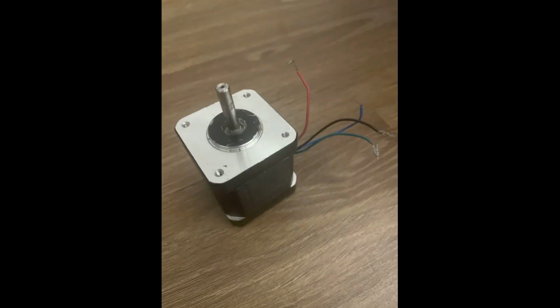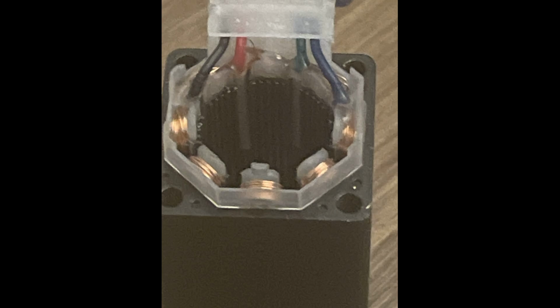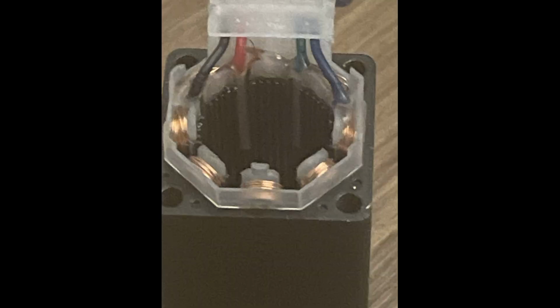A stepper motor has pairs of wrapped wire, coils, and a magnetic core that is shaped like a gear with the teeth being permanent magnets of alternating poles. You can tell which wires are paired together by touching the ends of any two coil wires together. If two wires are a pair, the shaft of the motor becomes more difficult to turn. To run the motor, the coils get sent current, which creates a magnetic field that interacts with the permanent magnets inside the housing. This creates attractive and repulsive forces, turning the armature to align the fields.